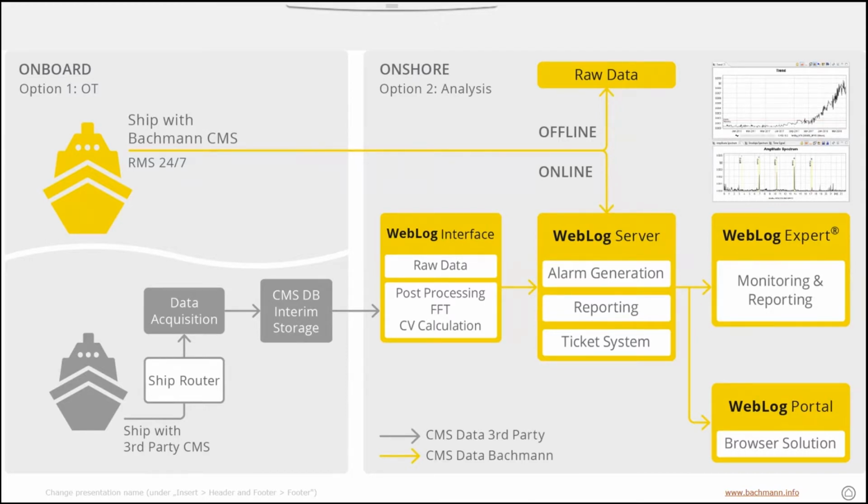So our control system, the controllers from Bachmann, can do a lot of the work near the machine. They're effectively edge devices. They can do all the vibration analysis close to the machine. But probably you don't want too deep an insight coming straight into your control room or your bridge or your engineers on site. On the ship, you want that data available for specialists to look at, but you want something a little more short term to keep you in the position of knowing what your machine's doing and collecting enough data to do more analysis if you need to.